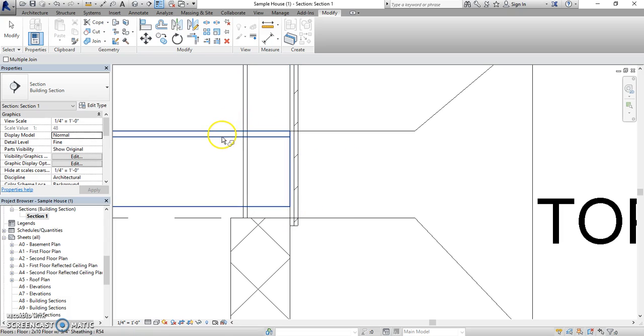We're going to do the same thing up here. We're going to click on the floor to consume the first floor wall that intersects with it, and now suddenly we have this nice finished face coming all the way down, all the finished material. We have our floor stopping at the outside face of wall stud. We have our first floor gypboard stopping at the first floor wall sheathing. Same thing for our studs.